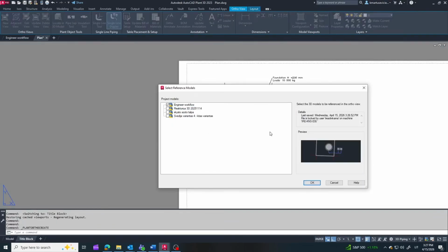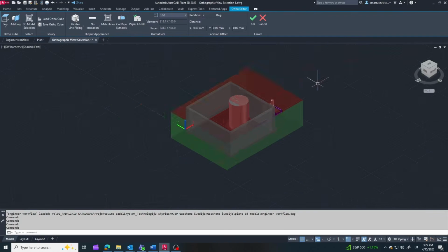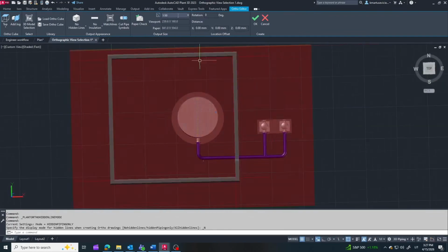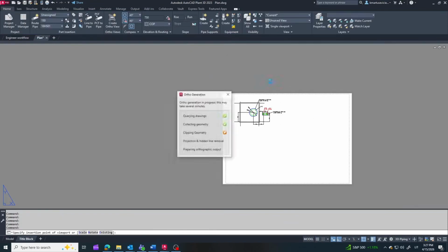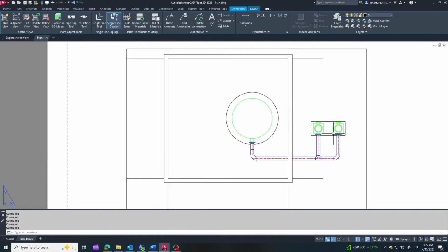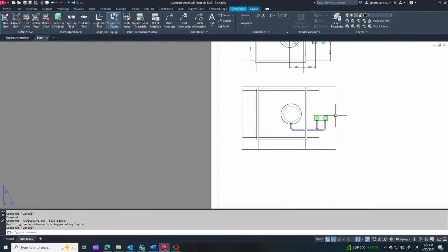How do we finish these openings? There are different solutions. A typical method is to fill the gap with rock wool and seal it with mortar or fire-resistant sealant. Don't be surprised. Sometimes, on site, workers will ask for drawings showing how to seal these openings. In many cases, they may end up doing it themselves.